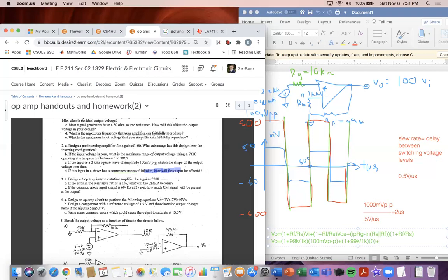And then the last one, he talked about the input resistance from the source. And so that's why I'm like, okay, we have an input bias current. So I did reference the manual, and we found that it was 800 nanoamps full scale range times that input resistance, which is 10K ohms, minus that 800 nanoamps, which comes again from that data sheet I showed you earlier.